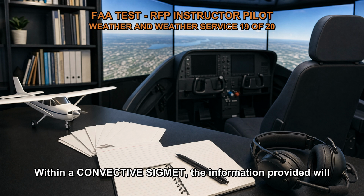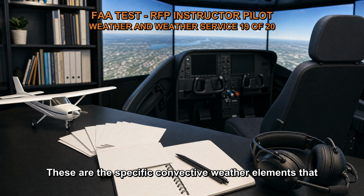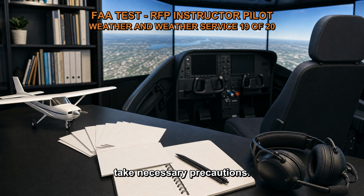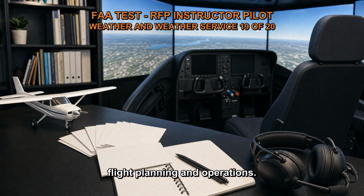Within a convective SIGMET, the information provided will primarily focus on the presence of tornadoes, embedded thunderstorms, and hail with a diameter of 3/4 inch or greater. These are the specific convective weather elements that pilots need to be aware of to make informed decisions regarding their flight routes and to take necessary precautions. This information assists pilots in identifying and avoiding areas of significant convective weather activity during their flight planning and operations.